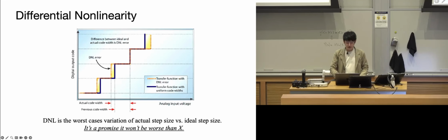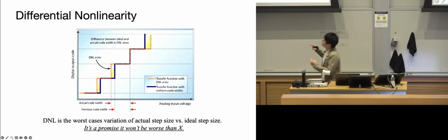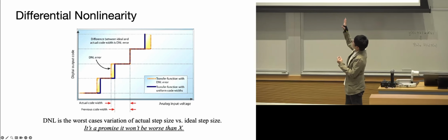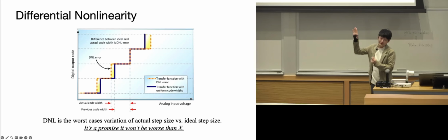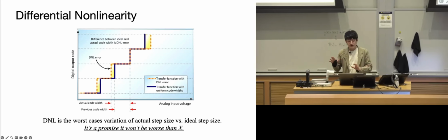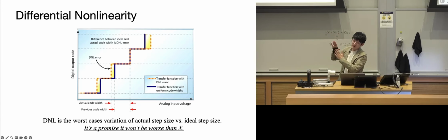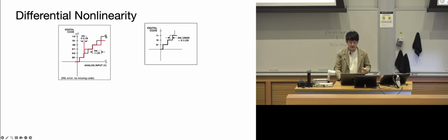We also have differential nonlinearity. This is a little bit trickier. It basically means that each of the step sizes can have a little bit of value shift in both directions. If this value is relatively small, then maybe it's okay. We can show you different cases.